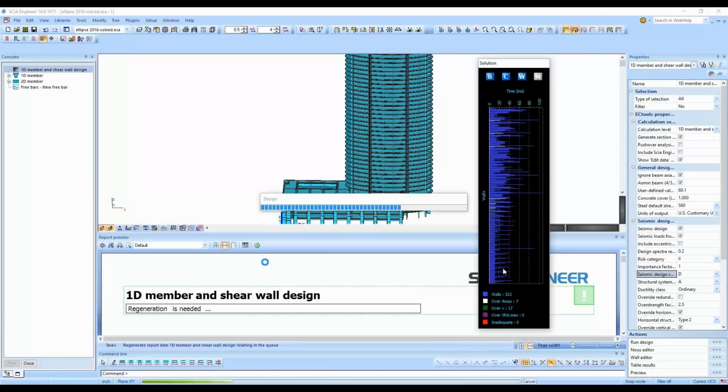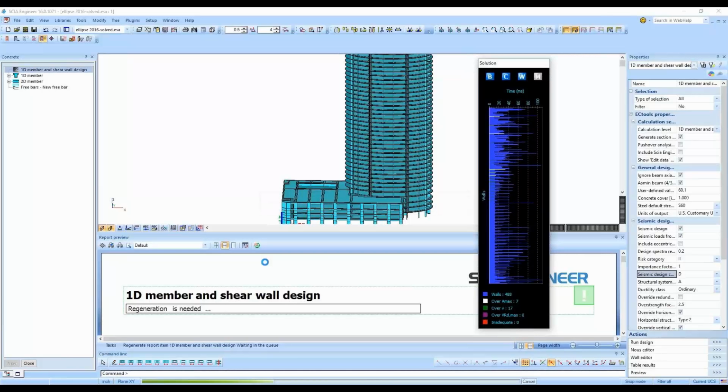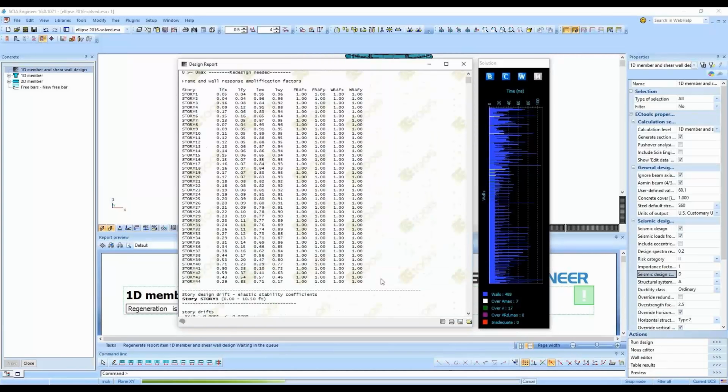As this finishes, you will see that the report comes up, and by clicking on any of these elements on the bar chart, the report directly goes to this element and you see exactly its dimensions, the axial forces from the design. Here we see the general design results. I will not stay much here because these are later on sent to SCIA Engineer.